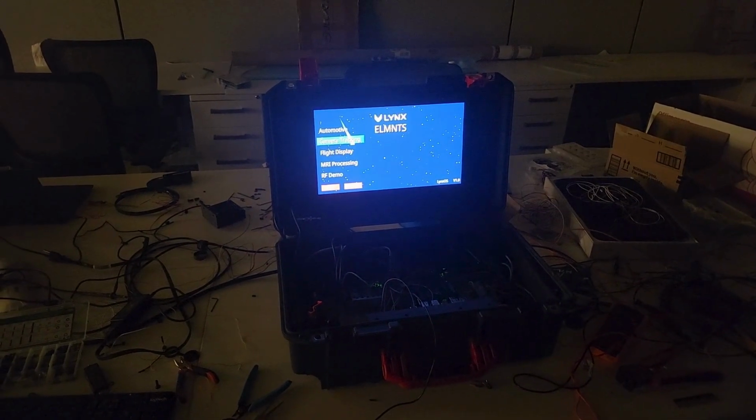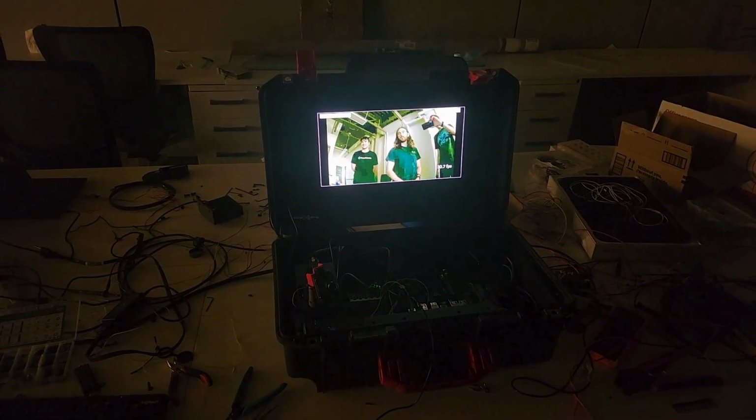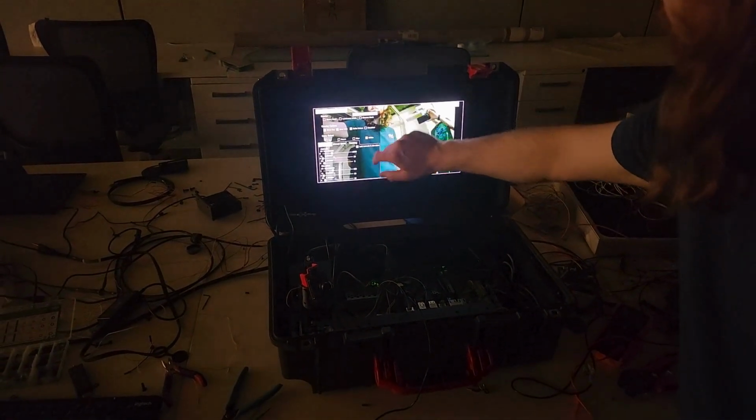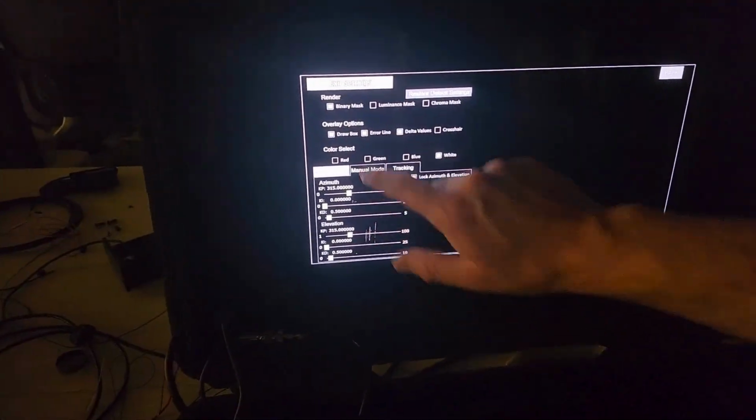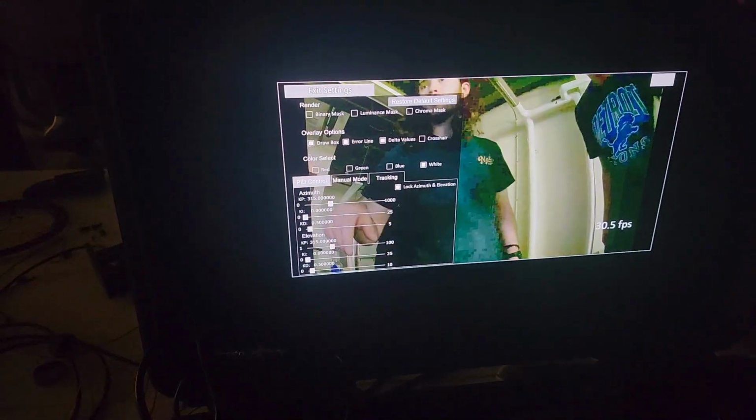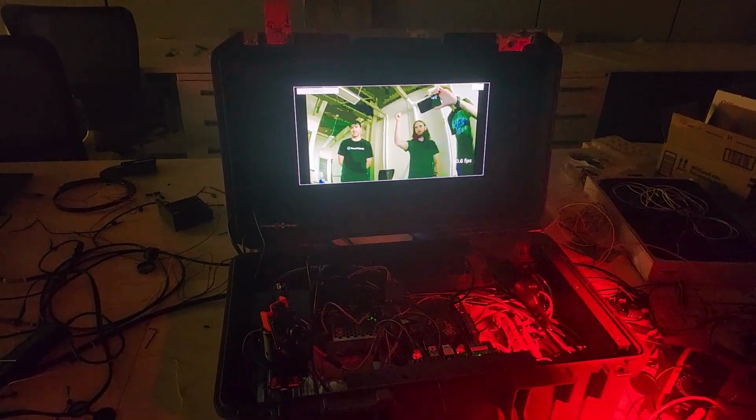Now we look at the camera tracking demo. For this portion of the video, we set the chroma and luminance values to track red light. Other settings can also be tuned here, such as adding PID to control the servo movement for the camera tracking